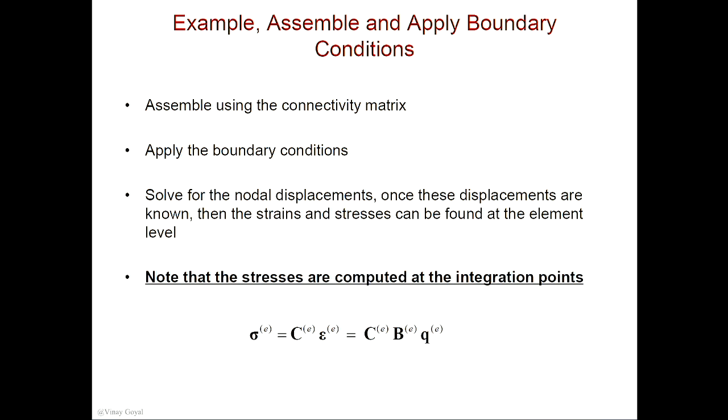So this is how you calculate stresses. Once you know stresses, you can now calculate the von Mises stress to predict failure of metal, or you can use a failure criteria of your choice if it's composites, right? Or max principal stress if it's a brittle material, and so forth.